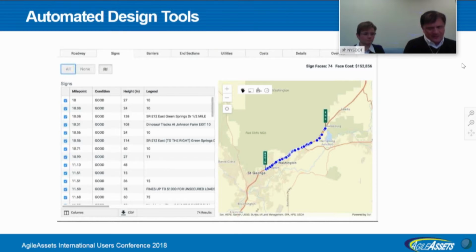It'll have the MUTCD definitions, so you will know what the size of the sign is. When you're doing these simple projects, you are really replacing in kind. So you are locating the sign, replacing the sign where it is, replacing the pavement where it is. It is pretty straightforward, and when you have all of this in your database, it's all available right there for you to be able to do your design project.